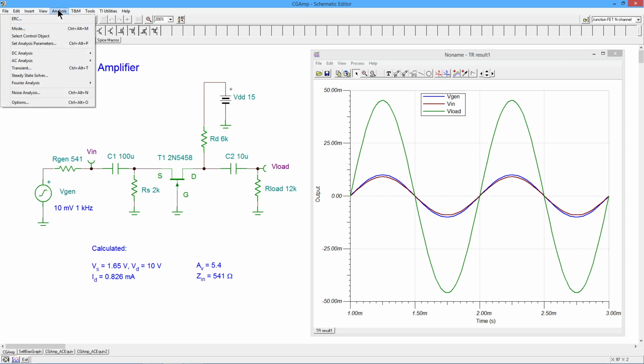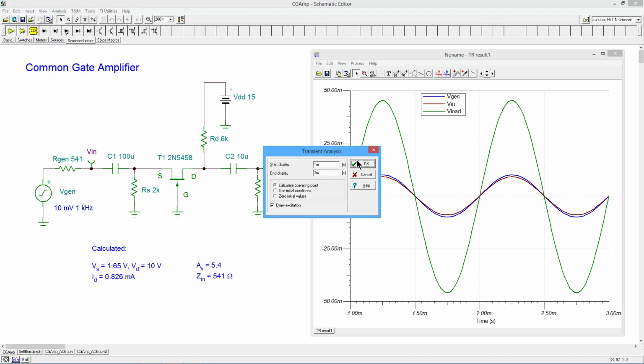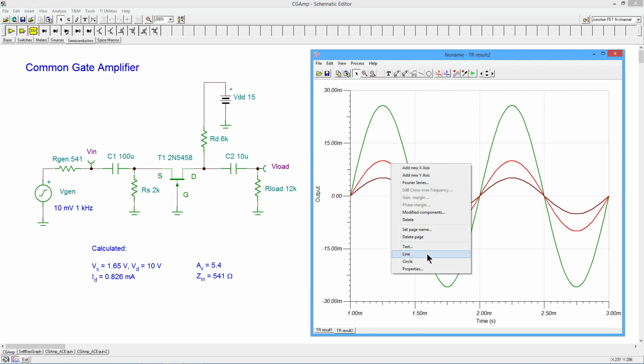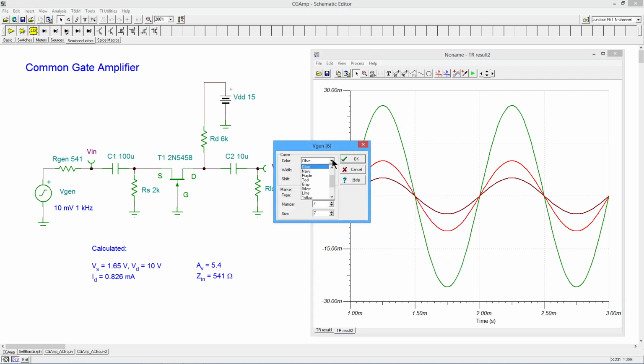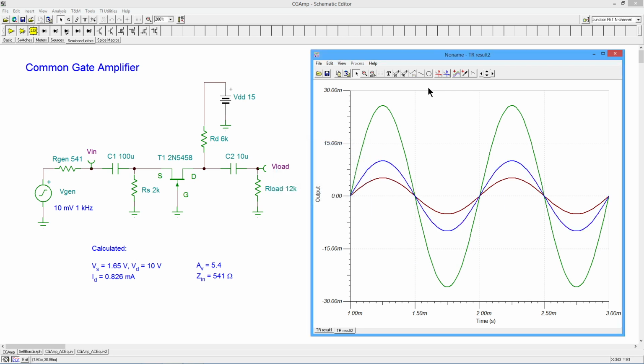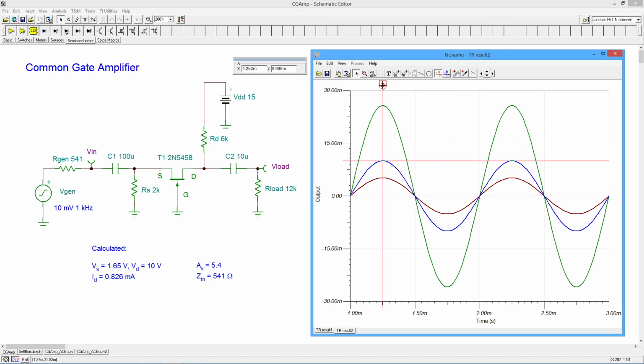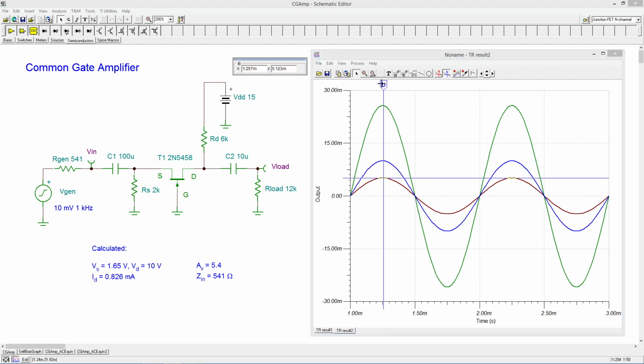All right. Okay, so let's go into the transient. Do this again, see what we get. Just to be consistent, I'm going to change the color on that one so there's no question. We made that blue. So that blue is supposed to be our 10 millivolts. And just for the sake of completeness, let's check that. 9.97, so 10. Now I'm going to grab the Vin.